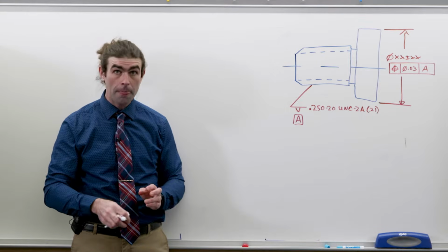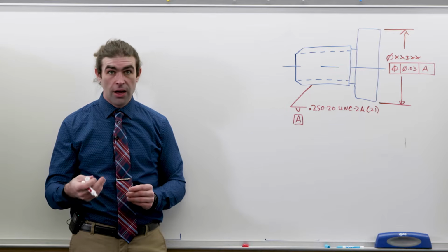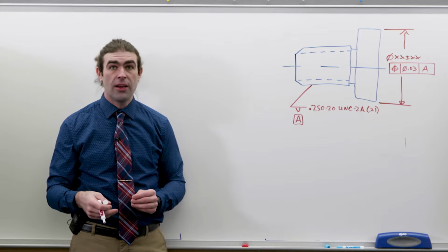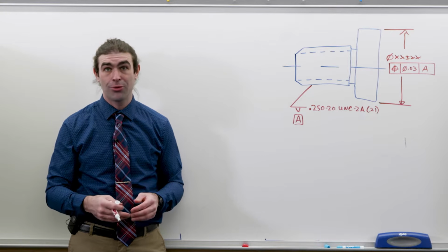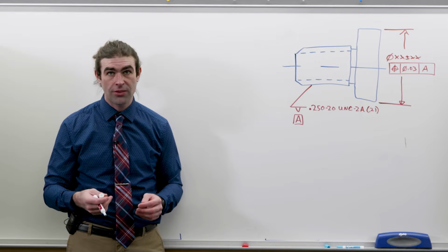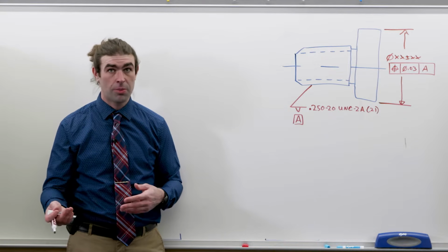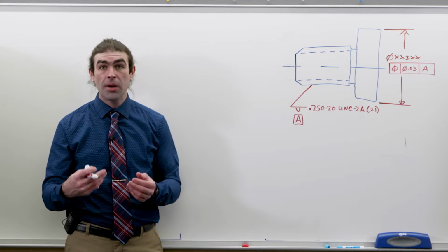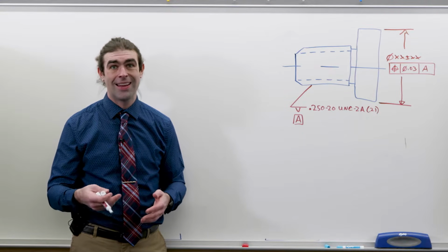Now, the tricky part is that when you go to inspect this, unless otherwise specified, the datum is the pitch cylinder, which is an imaginary thing in between the top and the bottoms of the threads. This requires expensive inspection equipment to capture, depending on the thread size. But it is the most functional because that is what's going to locate the thread at assembly.